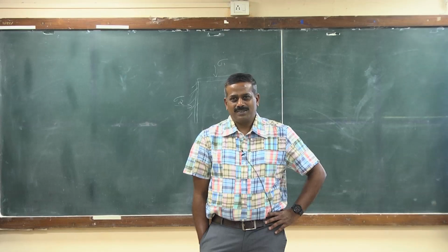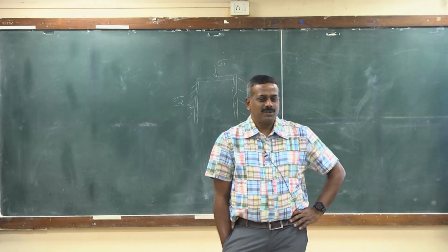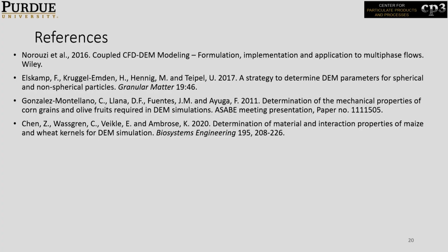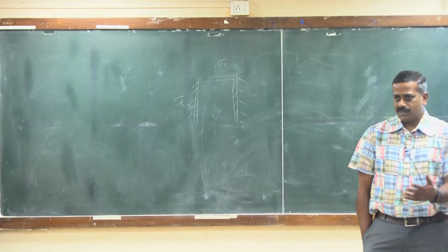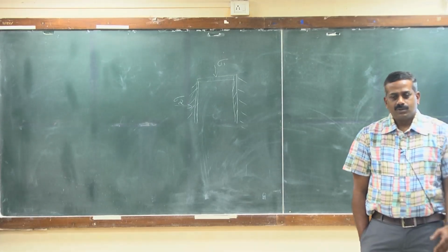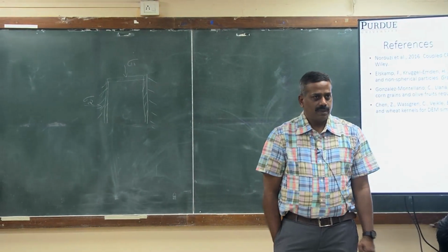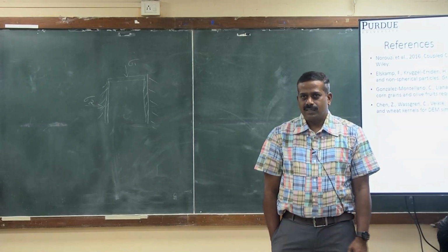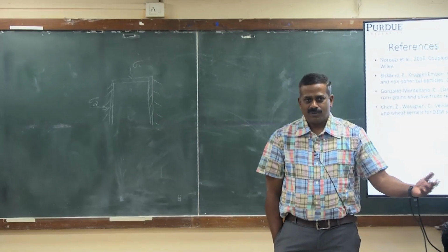Okay, so I will give the answer. We don't measure. It's very difficult to measure for small materials, so we assume. When you are doing modeling, you simulate with a range of restitution coefficient values, and through experimental validation, you find the appropriate coefficient of restitution. For larger materials too, we talked about lots of challenges in measuring it. So most simulations, when you see those papers, they don't measure. They do some calibration of parameters.